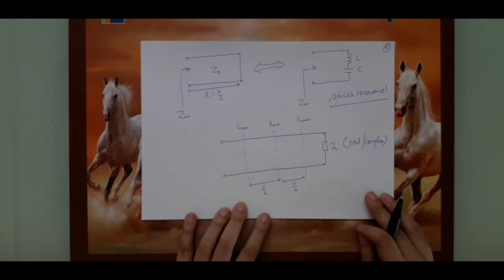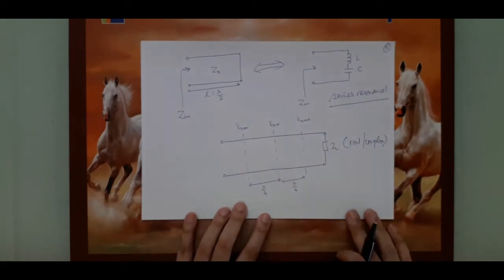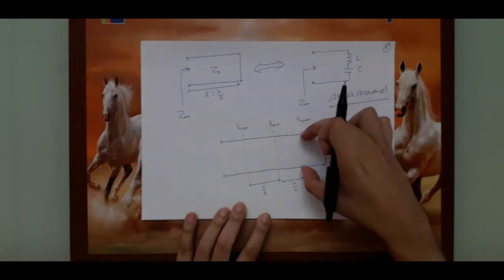Now the question is, how do we measure these voltages? How do you measure voltages in the lab? You simply take a multimeter or a voltmeter and connect it across the 2 points whose potential difference you want to measure. But that is not the case with transmission lines. If you keep a voltmeter, the probes of the voltmeter will also act like a transmission line.